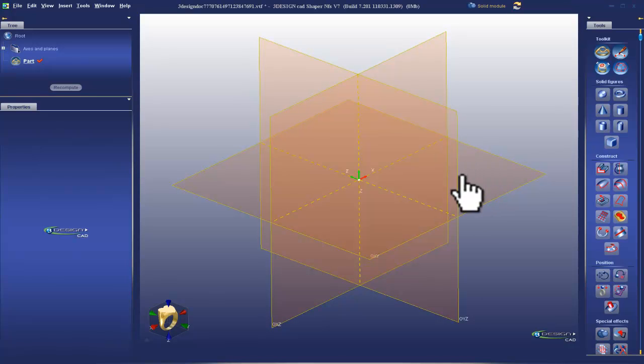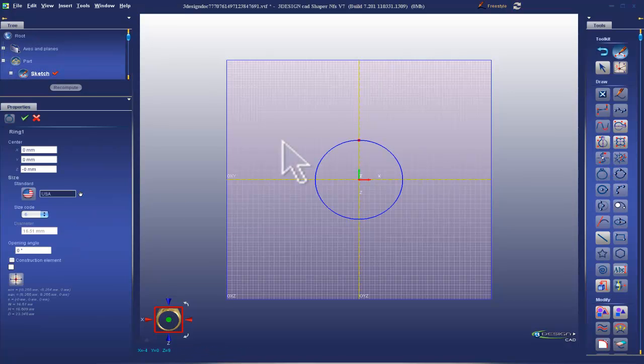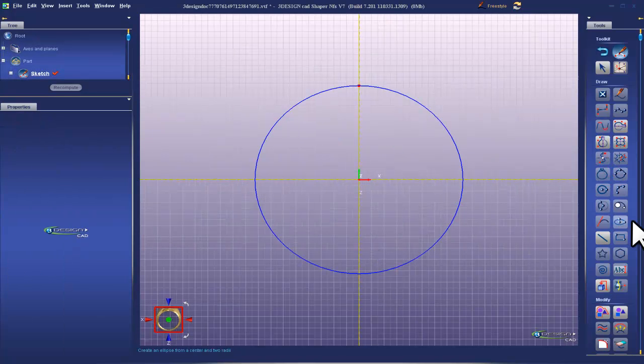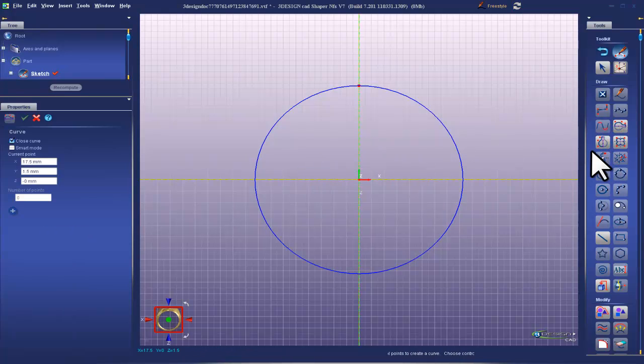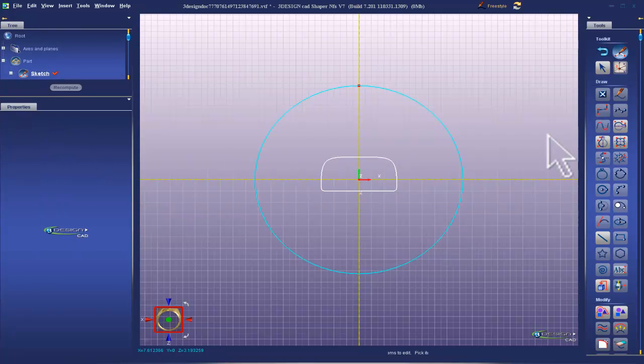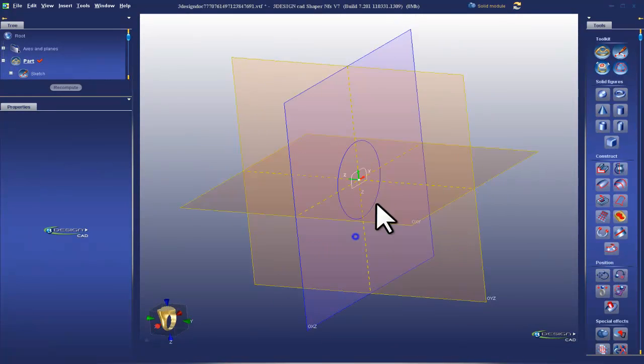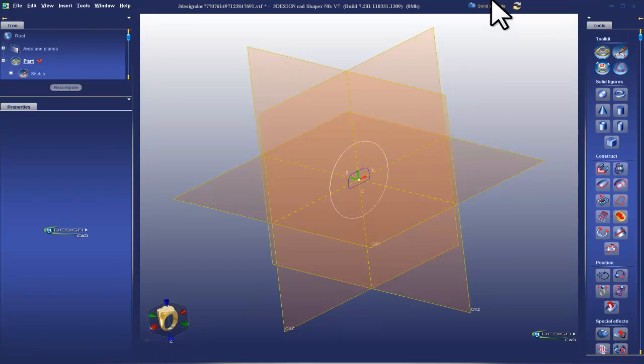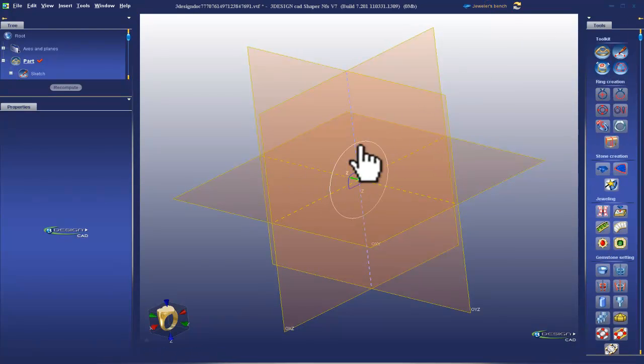Okay, cool. Now I'm going to show you another example of how Loft can fit into a construction. And I have to do a little bit of work first to get there, but I'm sure you'll all enjoy seeing me make a quick split shank. I'm going to use the sweeping wizard. Of course, I'm going to put my cross section in. Something like that is fine. Alright, so yeah, the sweeping wizard is in the jeweler's bench. So I'm going to click on the path and then choose sweeping wizard here.